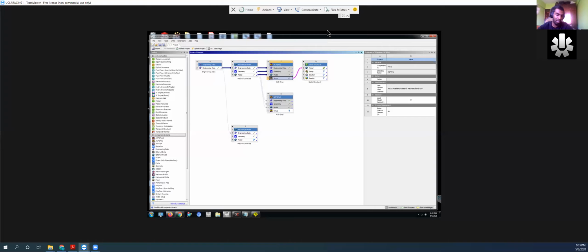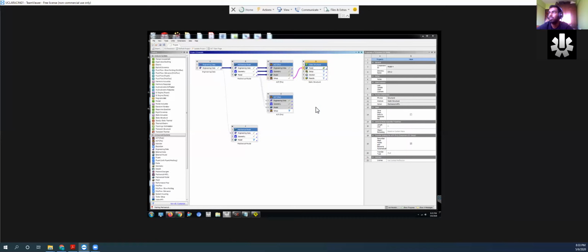That's why, if you remember, under the engineering data, when we input the values, we only cared about the X and Y values. We didn't care about the Z values, because we were going to do a shell analysis later on. So that's essentially the rationale behind choosing a shell. Once you've done that, you want to click on model again, and it'll start Mechanical.